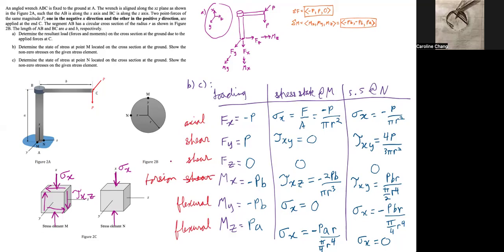And tau xy is shear stress acting on the x face in the y direction. Since it's positive, it will be pointing outwards, since we defined the y-axis to be positive pointing outwards. So it'll be like this. Using the head-to-head method and tail-to-tail method, we can draw our stress element as such.